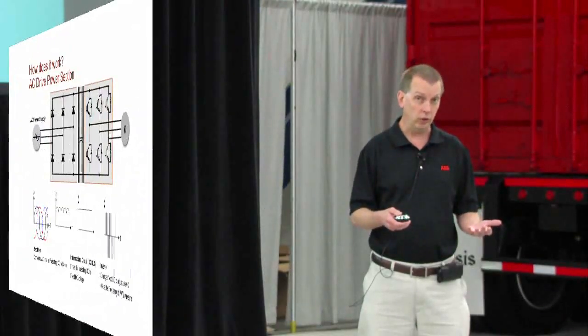Another reason you might want an AC drive is for energy savings. Pumps and fans, or what we call centrifugal loads, present the potential for energy savings. And the slower you can run them and still accomplish the purpose you had, the more energy you can save.